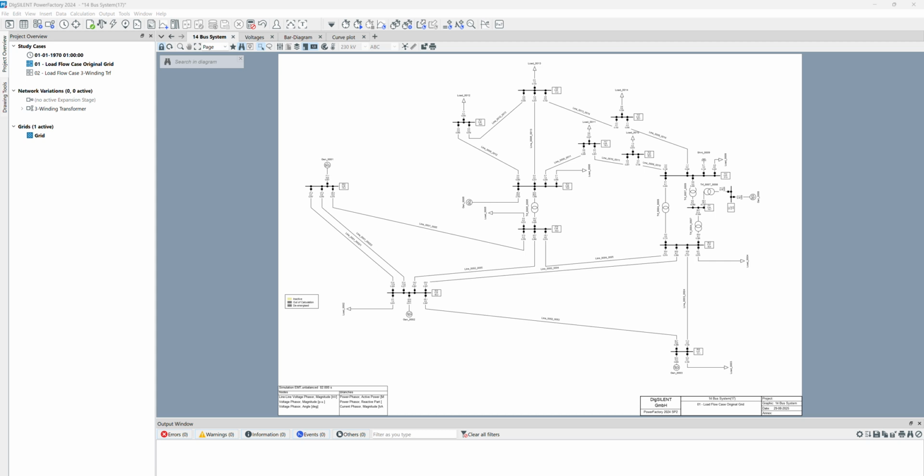Hello everyone, today we want to talk about a phenomenon in power systems with the name of missing zero crossing phenomena. So normally in power systems, when we have a fault or short circuit somewhere, for example in this line or any place, the overcurrent relay detects the fault and sends a trip signal to the circuit breakers. And the circuit breakers normally should de-energize the line during the time that we have the zero crossing point.